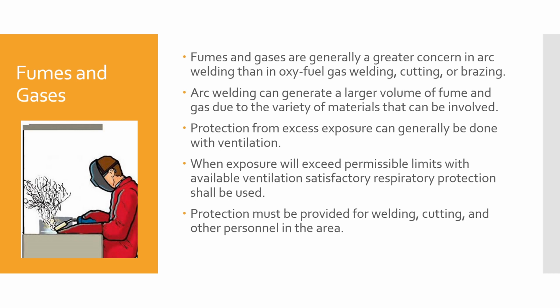So there's different ways that we can address the production of fumes. Ventilation is one of the better ways. Welding outside, or somewhere with a lot of air movement. I mean, it can kind of mess up your welds. We'll talk about that later, but fume extraction, they've come a long way with fume extraction, where you have these smoke suckers and you put them right over the top of your welding plume, the gases that are coming off your weld, and it'll suck them up right there at the source. So there's a lot of different options here.